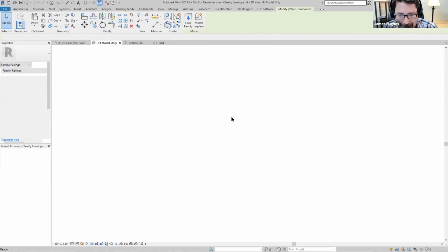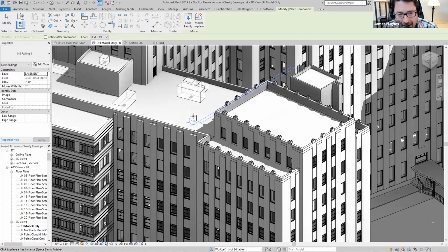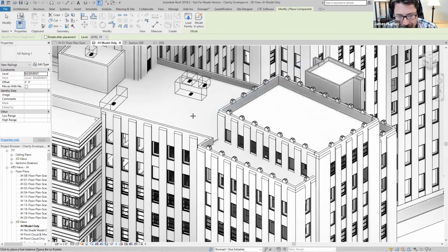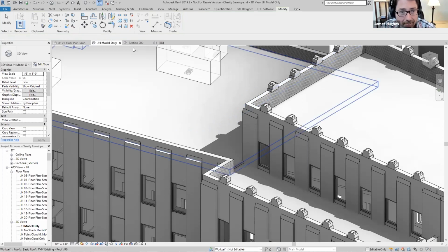And if it already has something named that, then it will go ahead and create it. Don't insert it in your 3D view. Do it in the plan view that you're working in. So for all of the exterior site elements, I just stayed on level 1. And that way it inserted back at the exact correct height. And I could just scoot it to the left or to the right and place it exactly where it belongs. So, I hope I didn't take too much time demonstrating that.